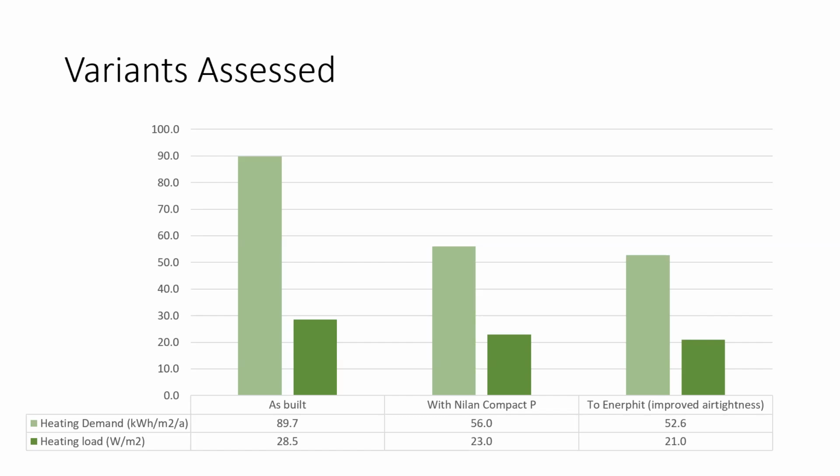And if the building was to be assessed using the energy demand method, you'll see the dashed red line is where your energy demand would need to be. So you can imagine, you've seen all the measures that Joseph has gone through to get the building to a certain level. What extra levels you would need to get your energy demand down to 25 would be extremely significant, and would likely lead to other issues such as hygrothermal issues or very little usable space left over.